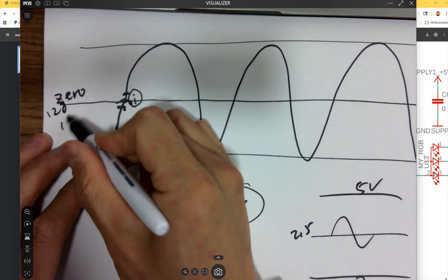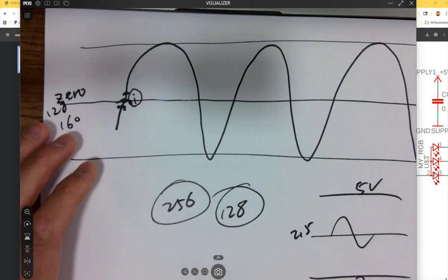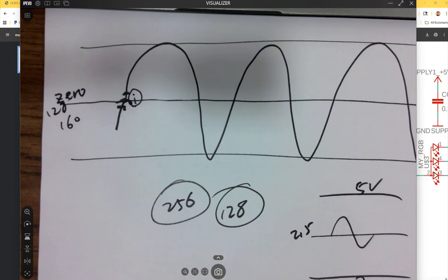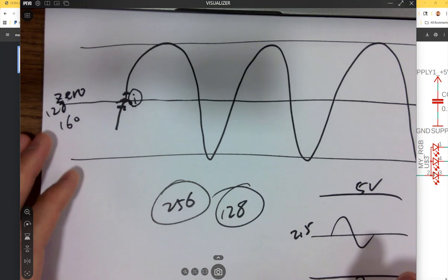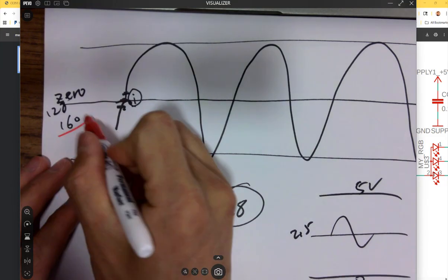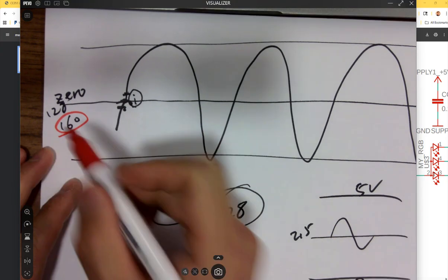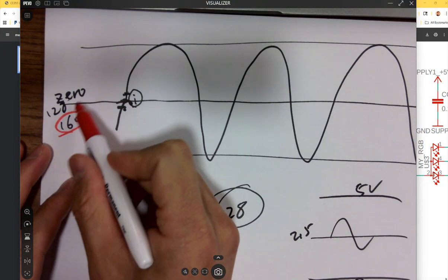What I'm getting is 160, which is fine. I'm just setting my zero point to be 160. You can test yours without whistling to it, right? Just see what the static voltage is giving to you, and then you set up your zero cross to that point. So I see 160 for my board. Yours is probably 130, 150, doesn't matter. So you can set it up as your zero point.